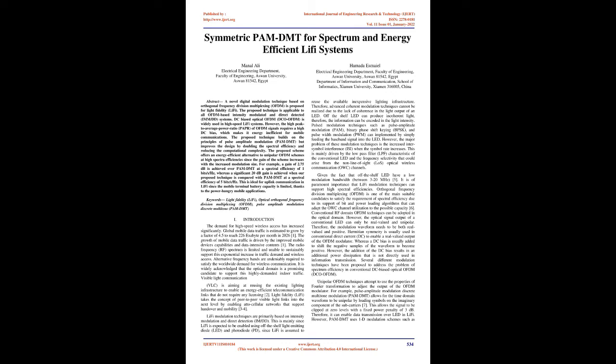This is ideal for uplink communication in Lifi, since the mobile terminal battery capacity is limited, thanks to the power-hungry mobile applications. Keywords: light fidelity, Lifi, optical orthogonal frequency division multiplexing, OFDM, pulse amplitude modulation, discrete multitone, PAM-DMT.